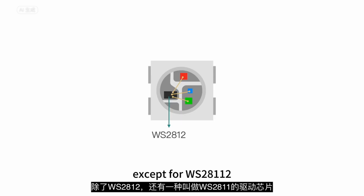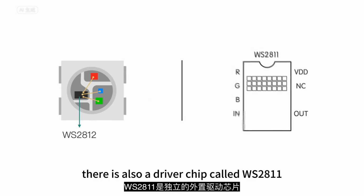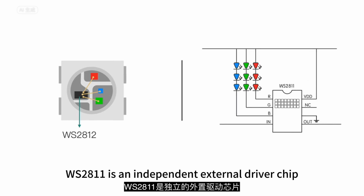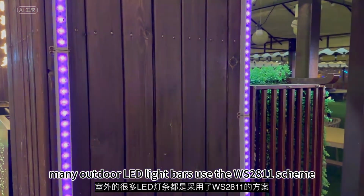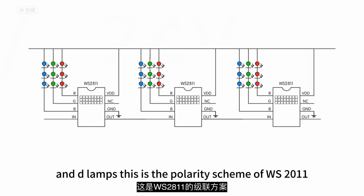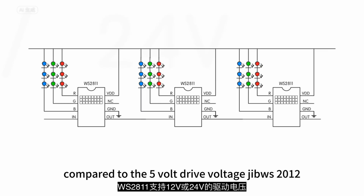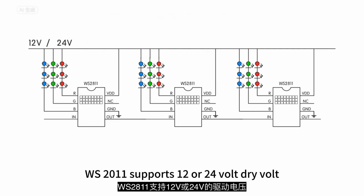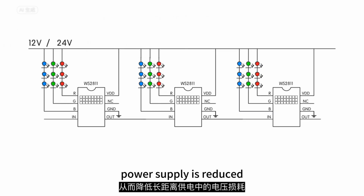Except for WS2812, there is also a driver chip called WS2811. WS2811 is an independent external driver chip, separated from the LED. Many outdoor LED light bars use the WS2811 scheme. You can see that there is a chip every few LED lamps. This is the WS2811 scheme. Compared to the 5-volt supply voltage of WS2812, WS2811 supports 12 or 24-volt supply voltage, and high voltage can effectively reduce the current. Therefore, the voltage loss in long-distance power supply is reduced.